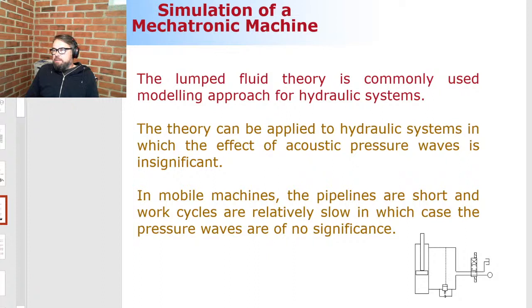All right, so as mentioned, lumped fluid theory is very often used, and even modeling software like Amesim is still based on a version of this lumped fluid theory, and it can be applied to basically all hydraulic circuits. It's very general.